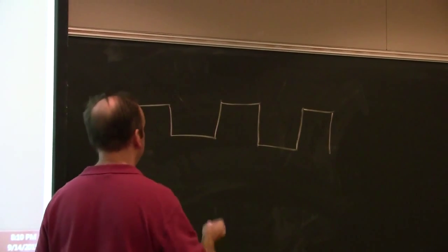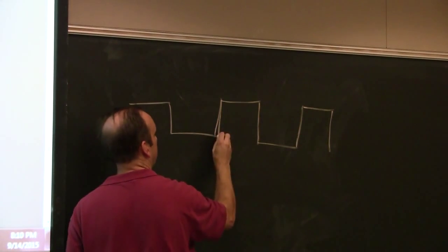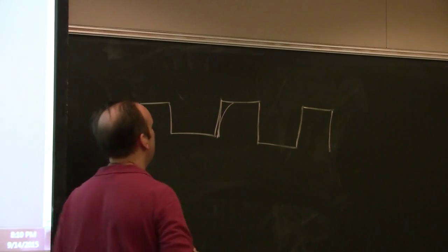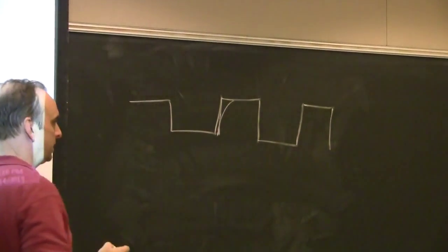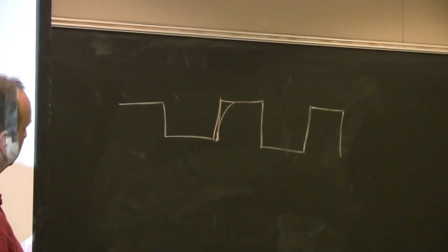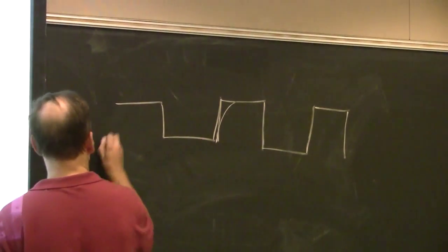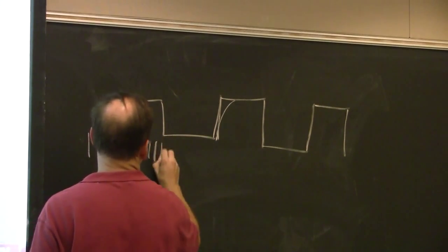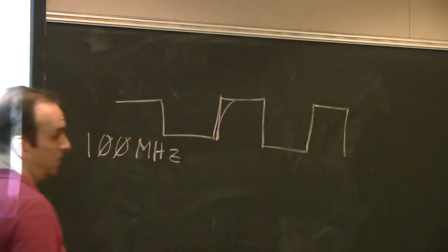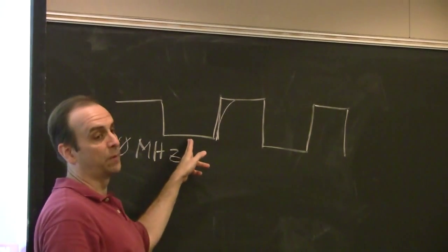And we know tonight that this doesn't exist, right? It actually looks like this. And the effect is more pronounced as you go faster. But what's the frequency content of that? I mean, let's say the clock's 100 meg. Does that mean the frequency of this clock is just 100 meg? No. It's probably a square wave since it's a clock.